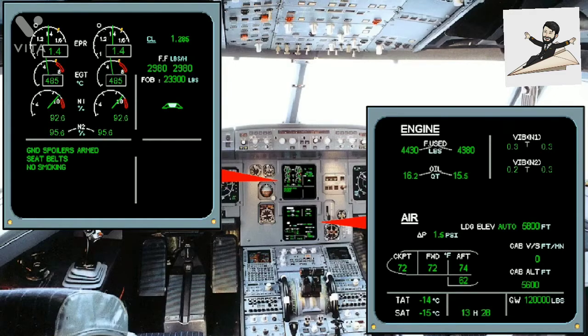Any of the conditions just mentioned can cause a compressor stall to commence, and as soon as it does, there is a partial breakdown of airflow through the engine. The indications of compressor stall can be any or all of the following. Fluctuations in the engine RPM.